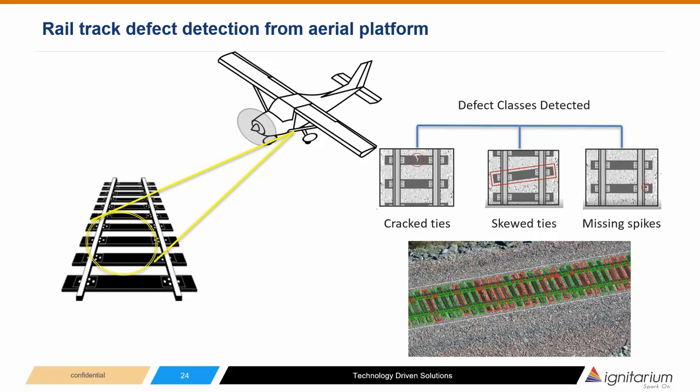The image on the bottom right shows the post-detection and classification results on a single frame. As you can see, it's a fairly busy image where there are 30 odd ties, twice as many plates, and several hundred spikes per frame. The spikes are not exactly very clearly visible. To achieve this, complex image processing followed by multiple neural networks running in parallel are called for, requiring significantly higher compute requirements than the dynamic ROI centering use case that we talked about earlier.